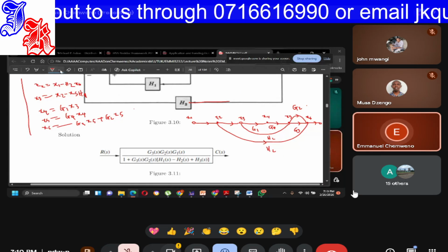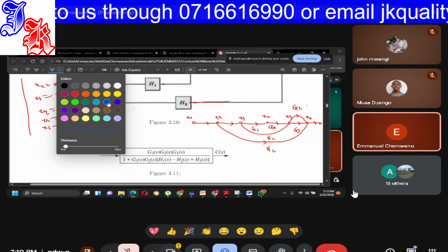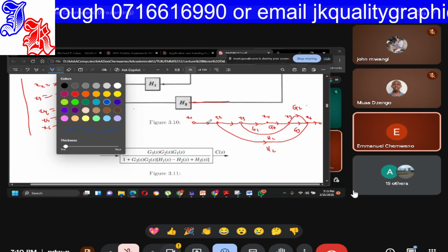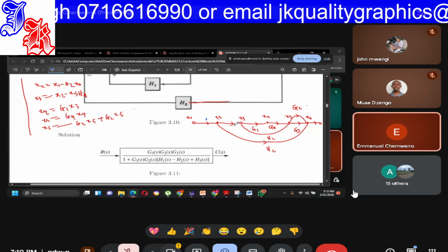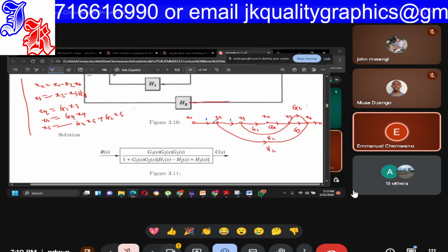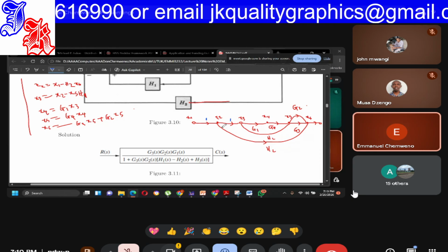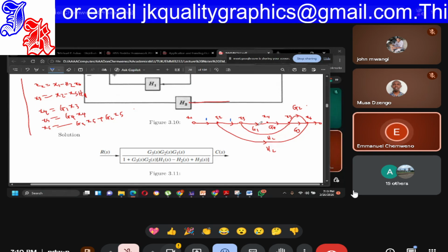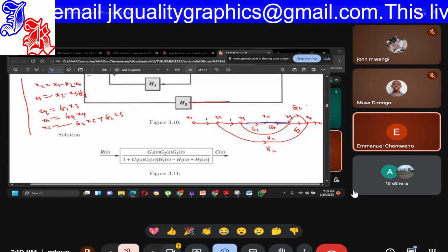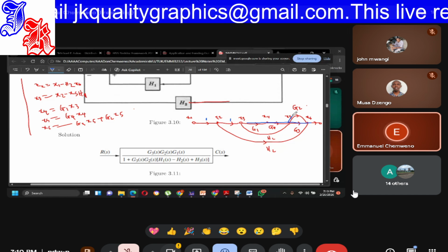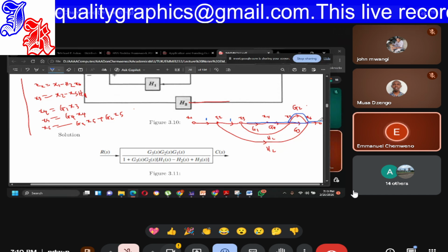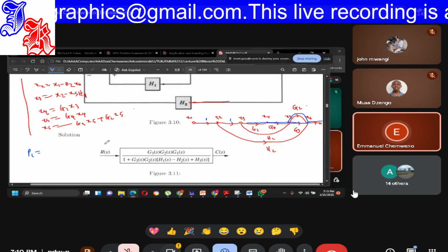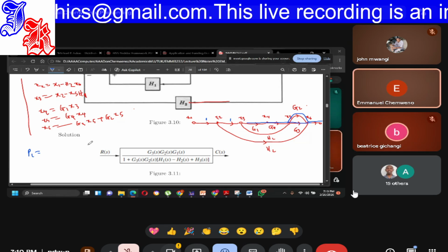So very quickly we identify our paths. We have one path. This was a 1, and this is a 1 also because of the coefficients of X1 and X2. So this is 1, 1. I have G1, G4. So here I have two paths. I have the one that goes straight, and the other one that makes that curve. So path 1 is equal to 1, 1, G1, G4,